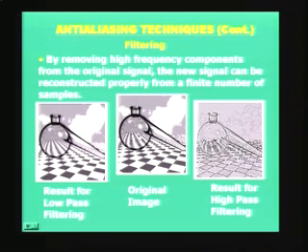Yes, it appears blurred compared to the original image, but if you carefully look, I would request you to come close and observe these areas. In one area here it is very light, you can see a blurring effect, but the effect of aliasing has disappeared. There was a strong effect of aliasing here which has almost disappeared in these ranges. So, this is one way, with the help of filtering: you need to use low pass filtering to avoid aliasing.